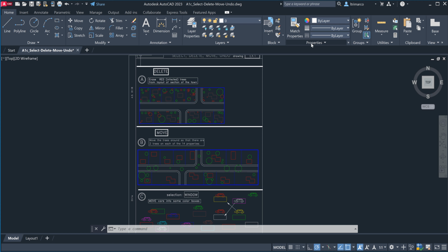Properties: every object we draw, every object that we create has properties to it. It has a layer name, or it's on a layer. It might be defined by a color, which actually is represented when we print as line weight. It might have a size, which of course it does, a width, a length, a diameter, on and on. And based on those properties, we can develop beautiful drawings, very detail-oriented drawings, very design-developed drawings, through line weights, through grayscales, through hatching, which are really important.